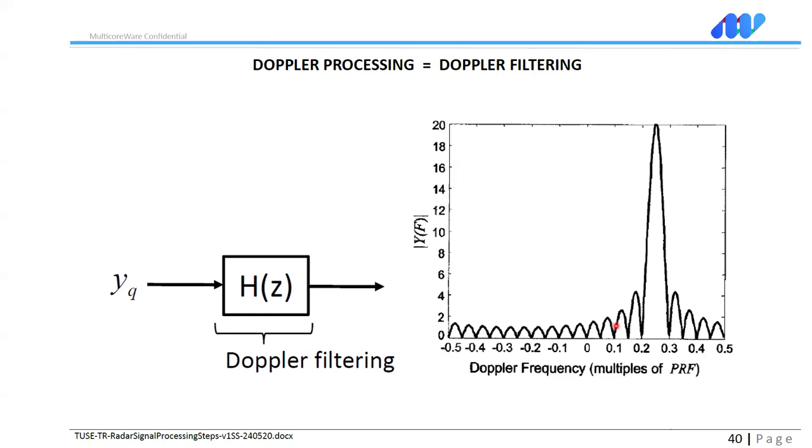In the fast time, we sampled the signal for ranges, and it's within the pulse. We just send the pulse, and just before you get the next pulse, you sample it. It's fast. And then you sample multiple pulses in the slow time, and you're going to feed it to Doppler processing, and that puts our samples into two dimensions. So this data is called the radar range Doppler matrix.